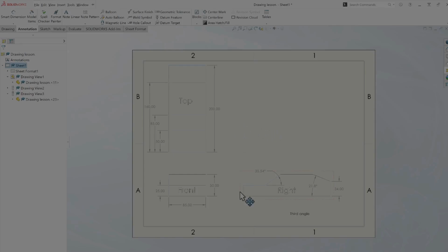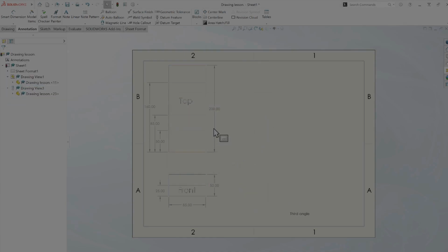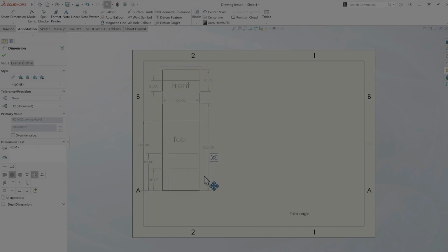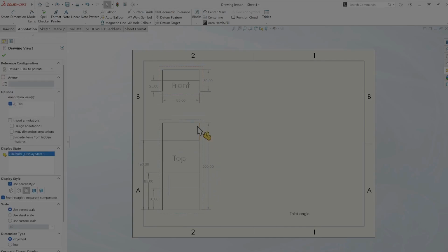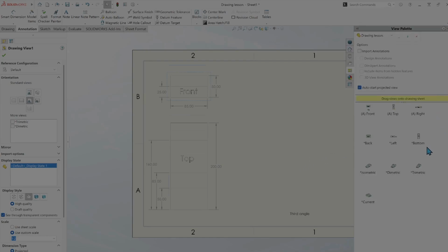Now we are putting this into action. So we have our car, and we'll start with the third angle. Like we explained earlier, in third angle, the plane is separating the viewer and the object. So if I view this object from the right side, this on your right here would be what you see. You'd be seeing the right side of the car.